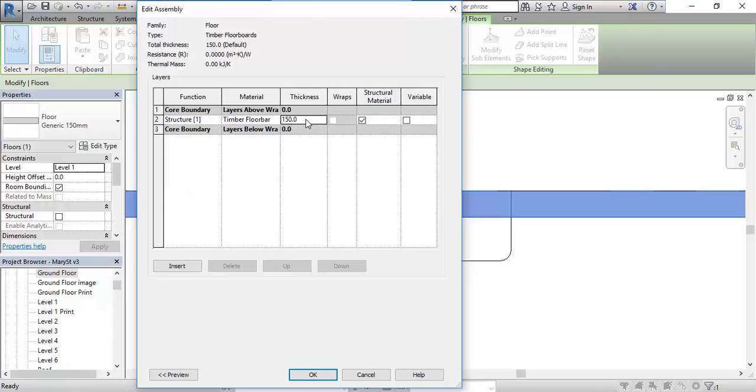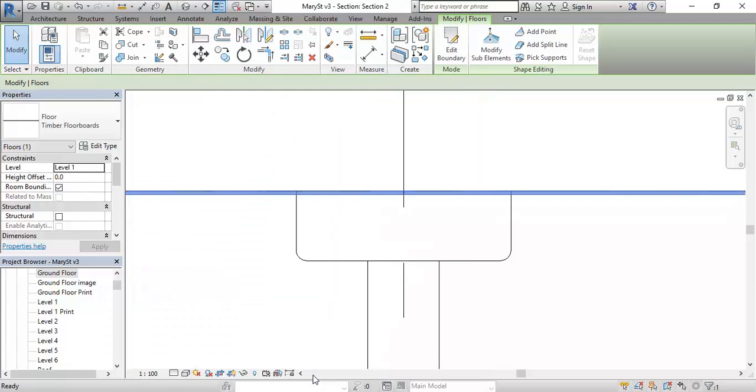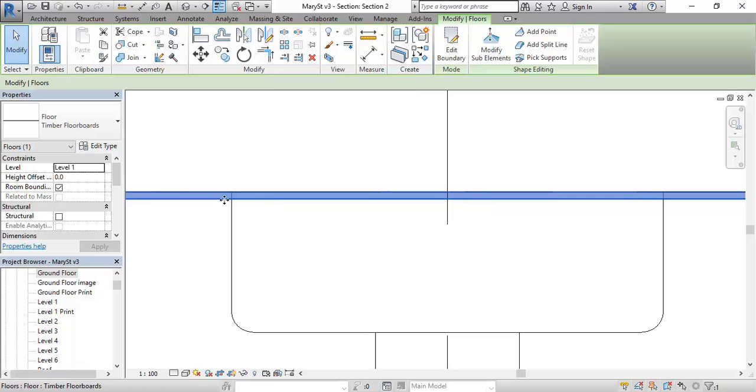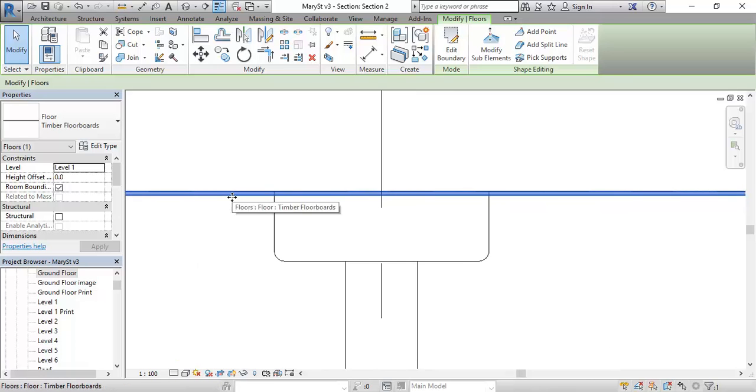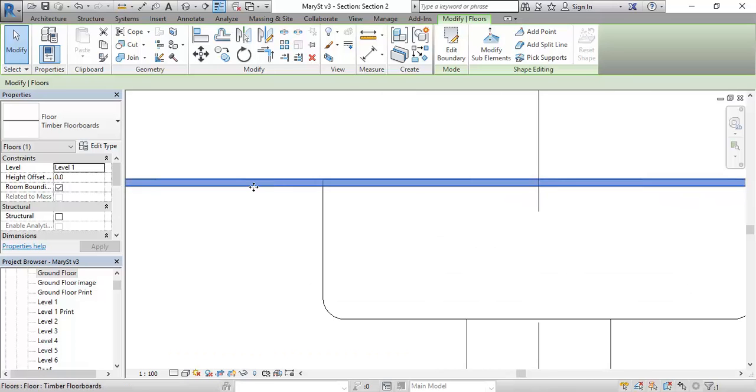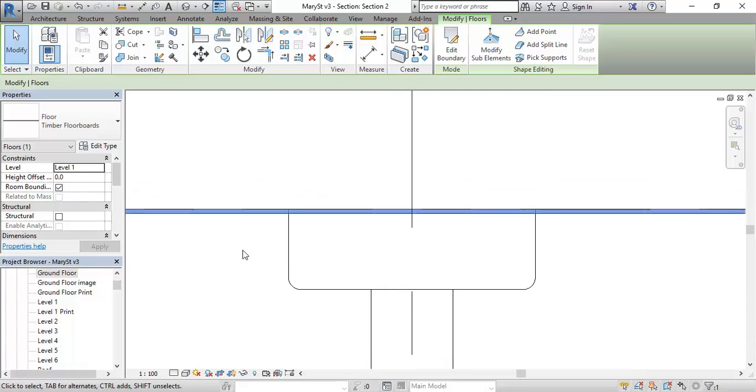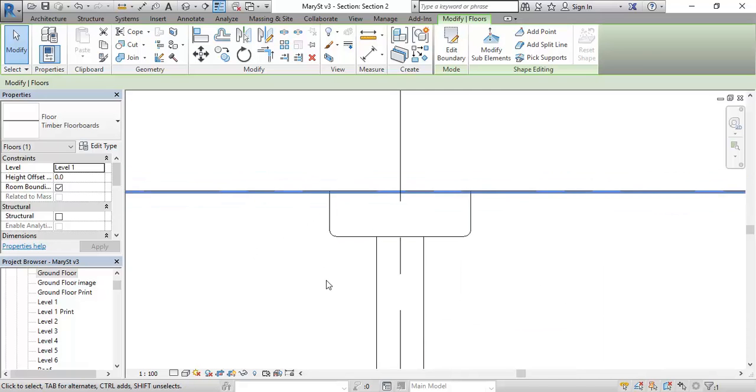And then I'm going to change the thickness to the thickness of a floorboard. So how thick do you think a floorboard is? Something you all would have seen. Piece of timber. It's about so thick. 15, 20 mil, something like that, that's right. So 20 mil, probably a good thickness. And so that's it. So it's a very thin floor. So I just wanted to show you this because this can be a really good way of making exposed floor structures. If you just leave the floor there for the floor lining, really. And then we're going to model in joists and things under that.